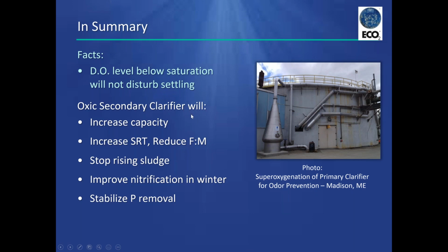And we have increased the capacity of the plant by making the secondary clarifier oxic and increasing the SRT. If wintertime nitrification is a problem, or if we need additional SRT to achieve stabilization, then that is accomplished without the addition of any additional tankage.